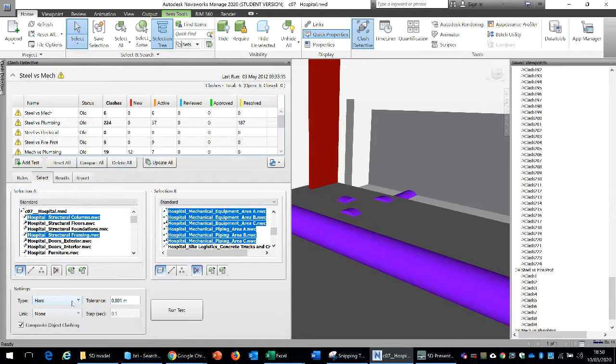So at the bottom, you could see there are different types of clashes indicated here. Now, the first one is the hard clash, which is where 2 objects occupy the same geometry or same space in the environment. So there's a physical clash which is taking place between the ductwork. So this could be a hard clash, or there could be a clearance clash where we want to have some sort of tolerance, maybe for different pipes, and if there's not enough tolerance or clearance, that could be highlighted. Or sometimes there are issues with the BIM model. There could be duplicate objects, so we would like to highlight that. Again, this is a specialist area, and those with a very good knowledge of production would be required to make sense of these clashes and to identify them, right?